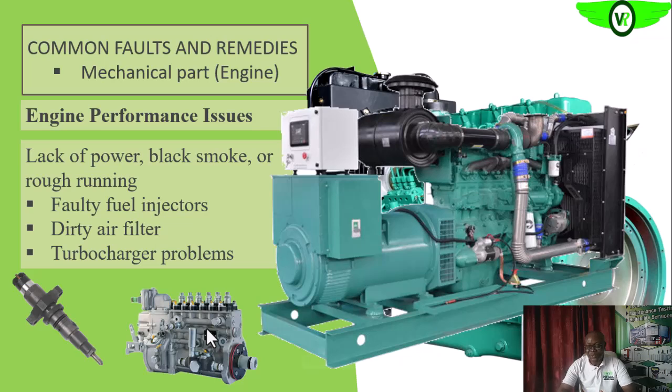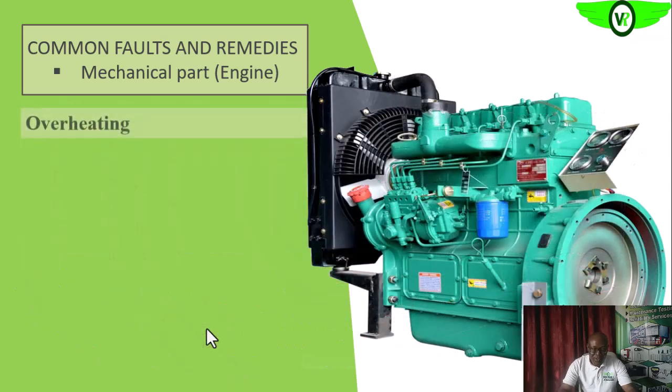Then if it goes to the compressor side, you see that oil will now be delivered to the combustion chamber. Okay, so that can result in a lot of white smoke also from the engine.